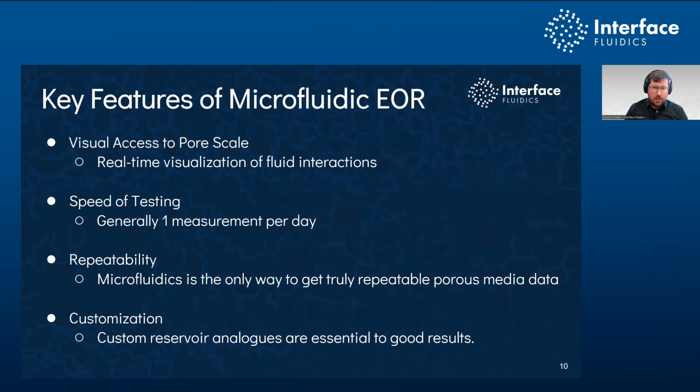So the key features of microfluidic EOR is that this is the only way to get real-time visual access to pore scale fluid interactions. So we actually see fluid front displacement advancement, we see pore throat trapping behavior, we see bypassing, and we can quantify all of those. The second is that the speed of testing is significantly faster and significantly easier than your traditional core floods, for example. We're making one measurement per day. Your core flood is making about a measurement per week or every 2 weeks.